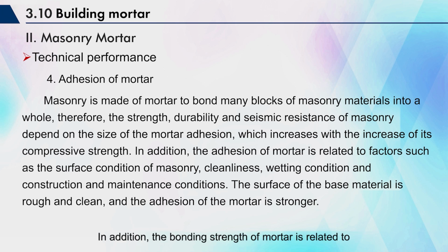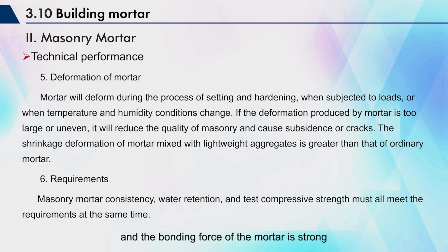In addition, the bonding strength of mortar is related to factors such as the surface condition, cleanliness, wetting condition, and the construction and maintenance conditions of bricks and stones. If the surface of the base material is rough and clean, the bonding force of the mortar is strong.